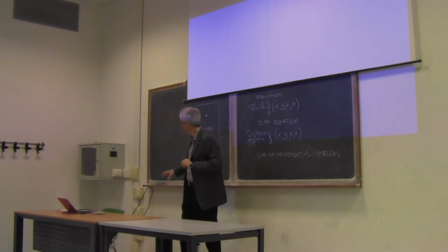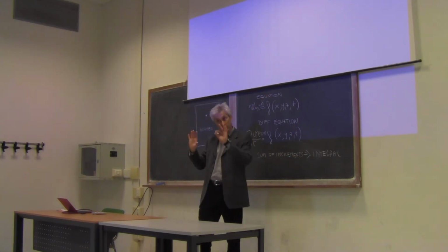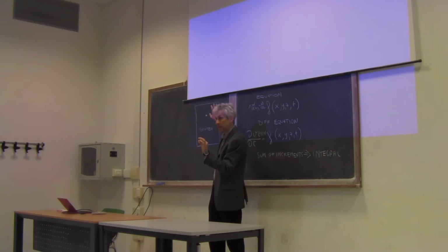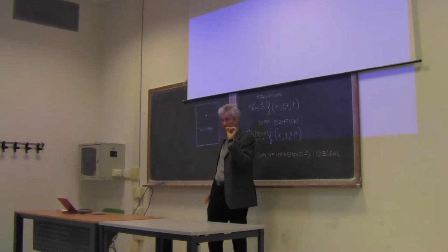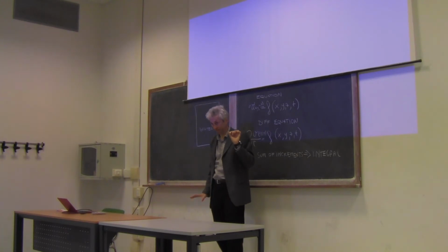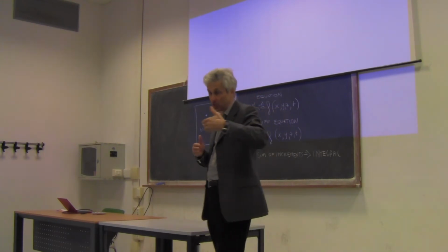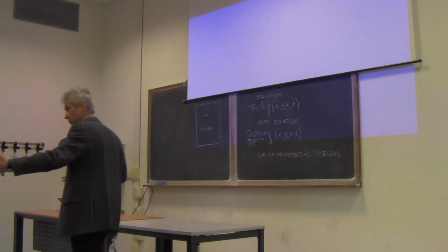So I need to write partial derivatives. And then, if I want to know a velocity value for all of this volume, I need to compute an integral. Of course, be careful: when you integrate over a domain, in this case over a space domain, the velocity value that you obtain is the average for this volume. Integration means computing an average along the coordinate of integration.